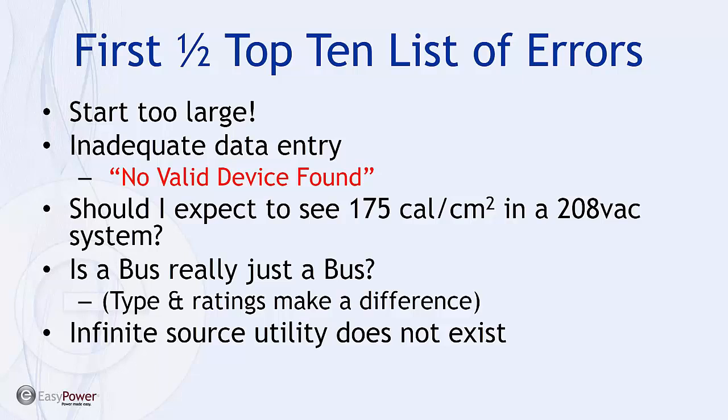Pointed out last time that there's the ability to amplify or better describe what type of bus, even if we're drawing in just a plain vanilla bus, and how we categorize that bus will affect the type and rating in terms of the dimensions, the air gap dimensions that are used in the Arc Flash calculations.